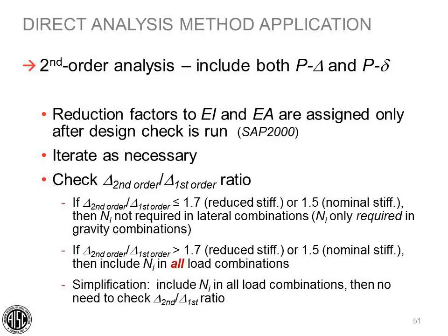So for a structure like that, then no, I don't think it's overly conservative to apply the 0.003 instead of the 0.002. On all the examples I did here, I applied the 0.002 just because that's the approach allowed by AISC and wanted to demonstrate that. But it certainly is a simplification to put 0.003 for all of those, and then you don't need to go through the tau b calculations.